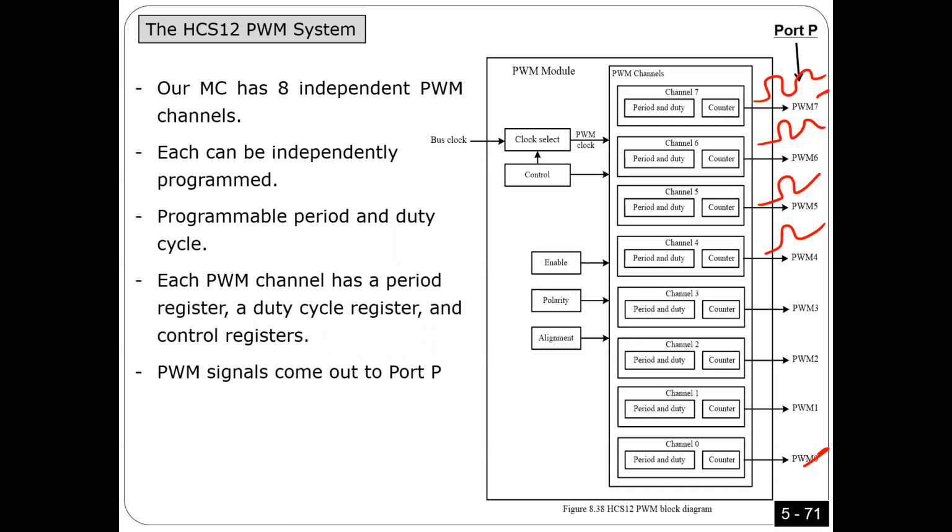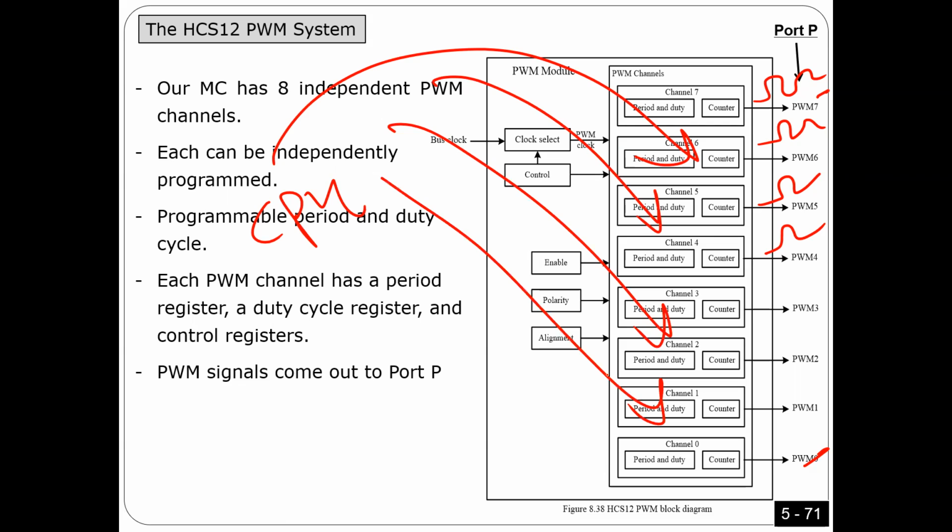The main advantage here, once it is a CPU, once you initialize the register, once you write some values to the register, I don't need any time anymore from the CPU. In output compare, there were interrupts, right? Here, no interrupts. So in output compare, I need some time from the CPU. Here, I don't need any time. Okay, that's number one. Second, I can easily change the duty cycle, as you will see right now. Any questions?